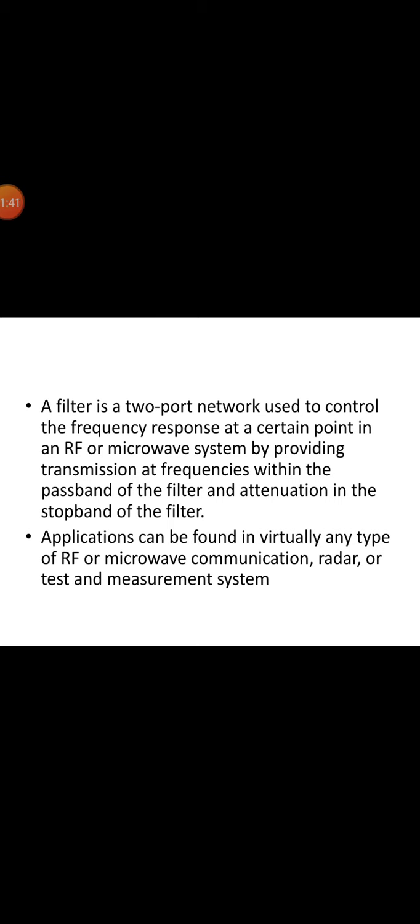Now let us begin our discussion of filter theory and design with the frequency characteristics of periodic structures, which consist of a transmission line or waveguide periodically loaded with reactive elements. These structures are of interest in themselves because of their application to slow wave components and traveling wave amplifier design, and also because they exhibit basic passband or stopband responses that lead to the image parameter method of filter design.